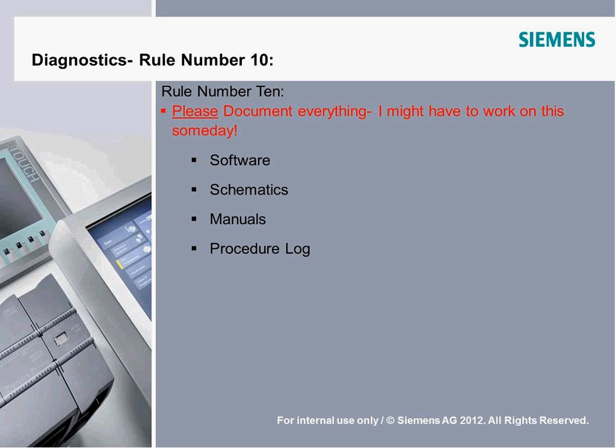If you can show your steps and your thinking as you went through diagnostics and troubleshooting on a machine, keep a log of it. Then the next guy that comes along, or yourself if you're back in there with the same issue again, can see what you tried, what did work, what didn't work, and all the other things that might help out next time, including improvements to the machine. You can put recommendations in there as well. Certainly you want to change things in a down situation, but recommendations for updates or changes that might help this machine work better are also good things to jot down.